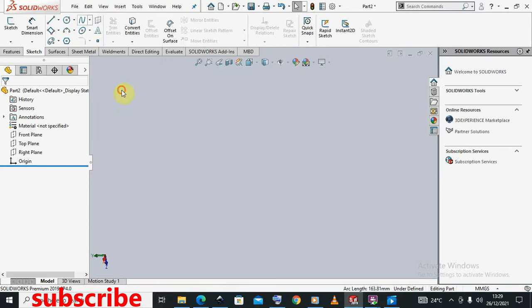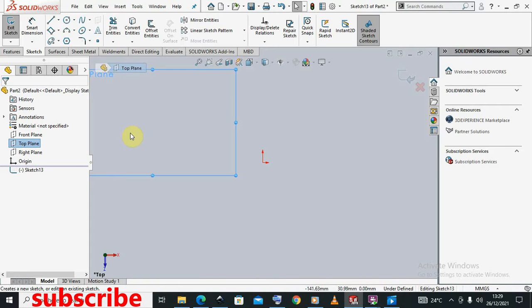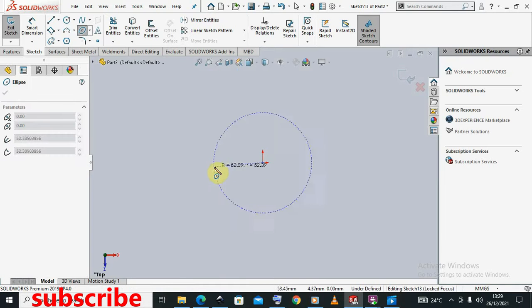Alright, so like we've been doing before, you will always start with the location of your sketch, or where I want your sketch to be. After selecting the plane, you come here, say ellipse. So this is direct. By that I mean that it starts from the center where you're seeing that small point. That's the center, and after clicking that center, that's the left click, you will drag your mouse and move outwards.